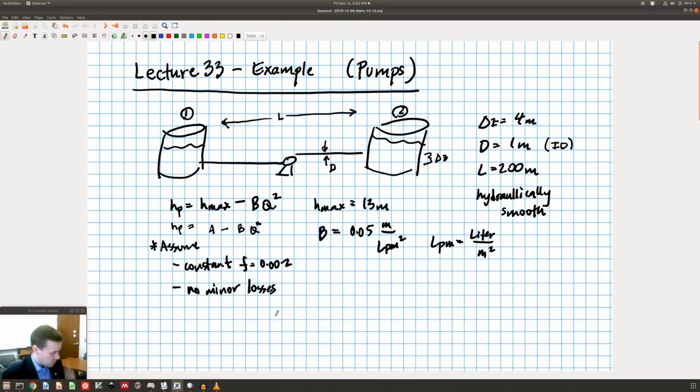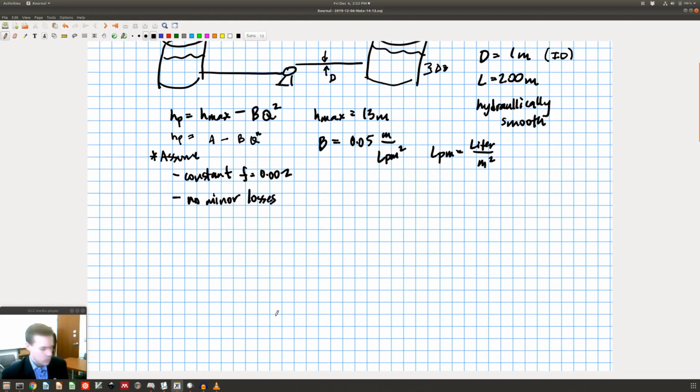So how are we going to solve this problem? Well, we start out as we do in all of these cases, and we write down Bernoulli's equation: delta P over rho plus delta V squared over 2 plus g delta Z equals the shaft work divided by W minus the viscous losses divided by W, where W is the mass flow rate. Okay, and this is the engineering Bernoulli equation. Excuse me, I said just Bernoulli earlier, but it's the engineering Bernoulli equation.